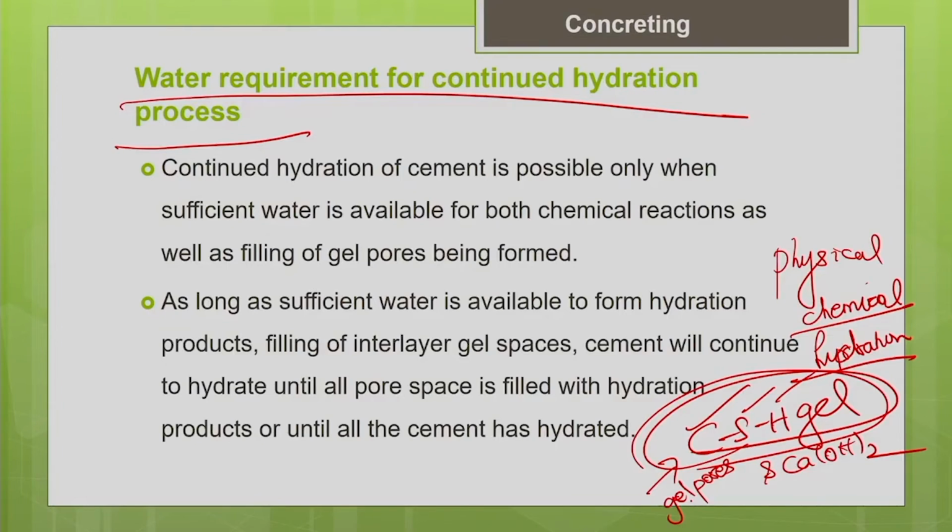Okay. So, that is very important. Then only your hydration will be complete. So, that is what I said: for filling of the gel pores in the hydration products also we need water, that is called as physical hydration.